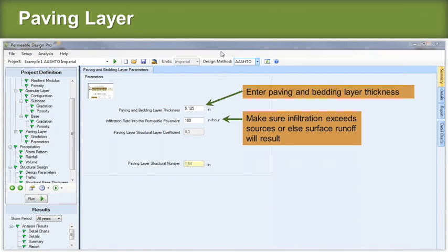And so that's why it's 5.125 inches here. All pavers come in metric units. They're manufactured by equipment that's all built in metric units. You can have 6 centimeter, 8, 10, 12 centimeter pavers, but this is the US conversion of that.